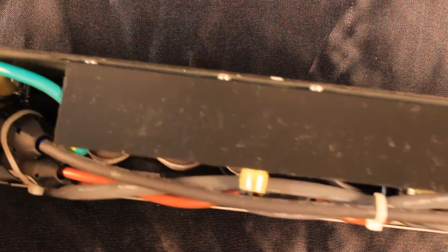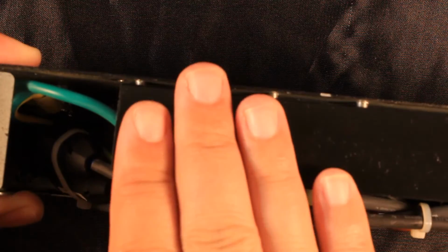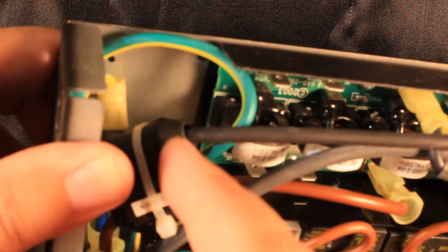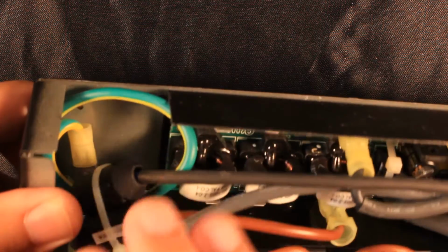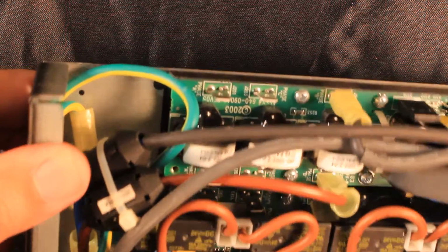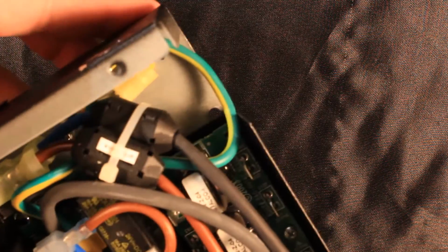They have also done a really nice job of using this formed sheet of plastic, which is most probably bent when it was still hot. And this plastic runs below this whole PCB, which is carrying the 230 volt AC, the mains voltage. So it means that they really took care of having a good isolation between the PCB and the metal chassis itself. In addition to that really nice ground wire there. I mean, come on, that is just awesome right there.